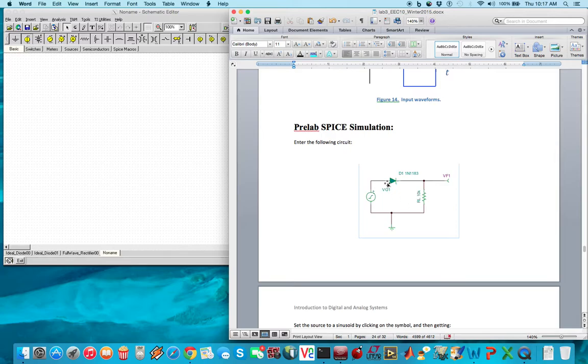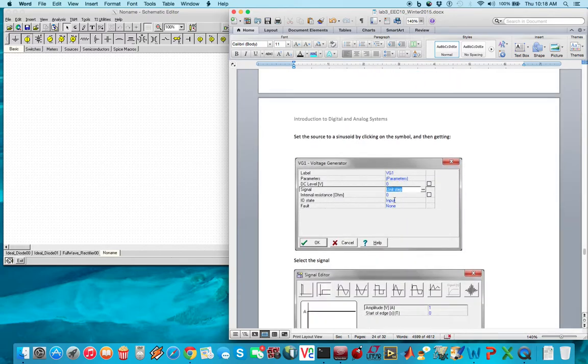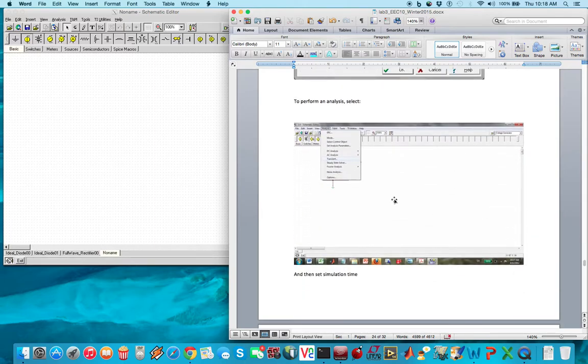through. So the reason why is, remember, the ideal diode turns on when you have a 0.7 or 0.6 volt, basically from here to here, positive drop across it. And so if this is at 0.7, this will be at 0 and it's barely turning on. If this was at 10 volts, this would be at 9.3. So as you're passing a positive sine wave, it'll be basically replicated here on this VF1 output pin. And as you go negative, this guy is reverse biased, turned off, goes into depletion region. You'll learn later what depletion region is in a different class. I think it's 140A.